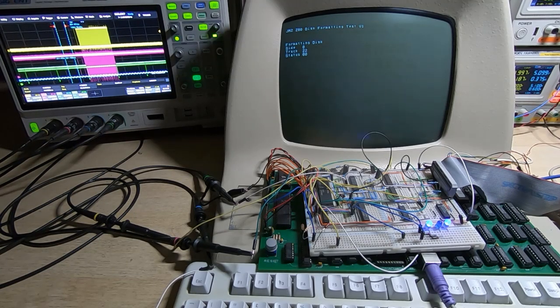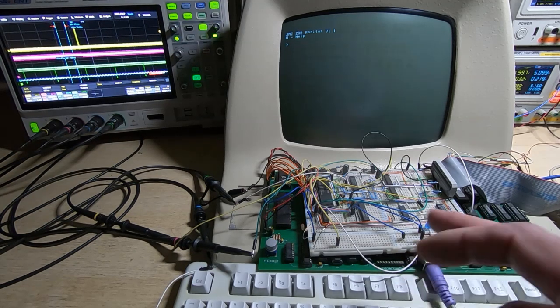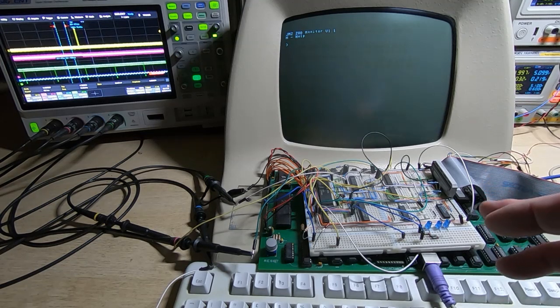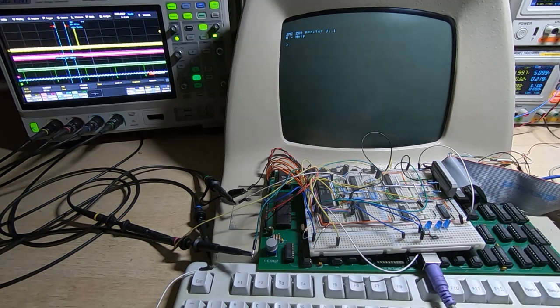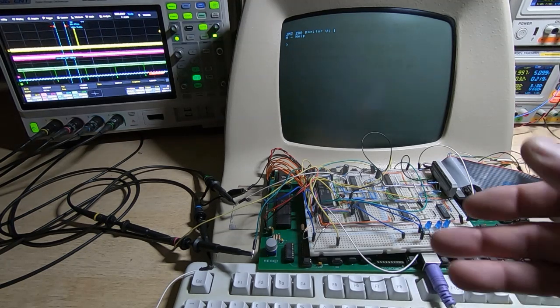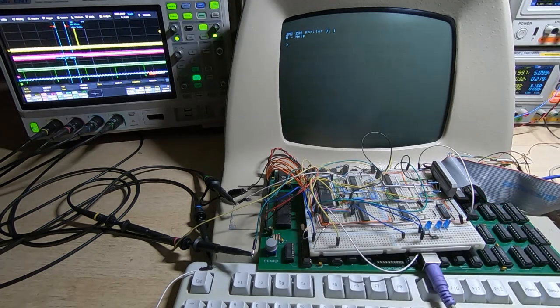Okay, we'll try reading that back. We're going to try reading track 0 sector 9, that's what's coded in the program at the moment. We'll try changing that in a minute and reading a different sector. All the sectors should be formatted. I should point out that rather than putting just general filler information in the payload, I've actually put some text in there so I can make sure that we're not just repeating the same bytes. So we should see some text appear on the screen when we try and read the sector, and it will show hopefully 128 bytes of text.